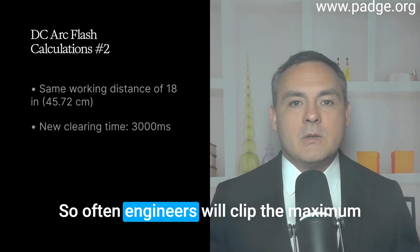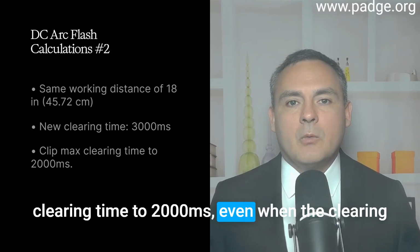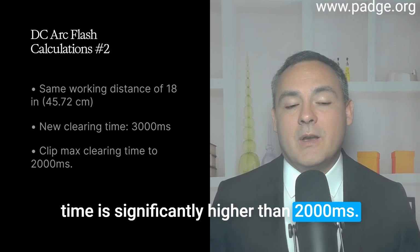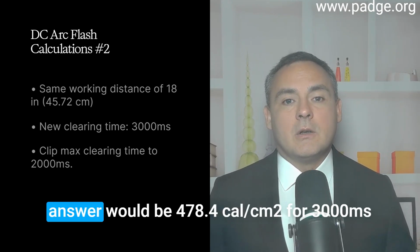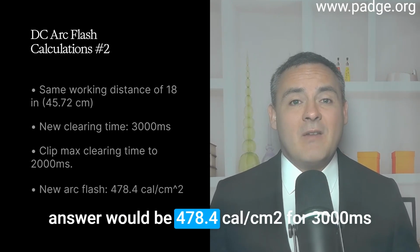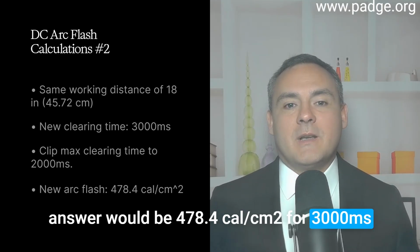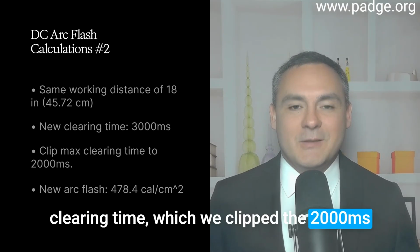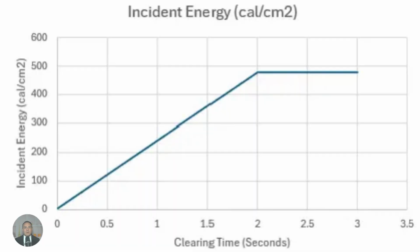Often engineers will clip the maximum clearing time to 2,000 milliseconds, even when the clearing time is significantly higher than 2,000 milliseconds. This practice is often justified. So, the answer would be 478.4 calories per centimeter squared for a 3,000 millisecond clearing time, which we clip to 2,000 milliseconds because we know we can justify that. Notice the plot I created to show how the maximum power method for DC sharply rises, and then I clip it at 2 seconds and beyond.